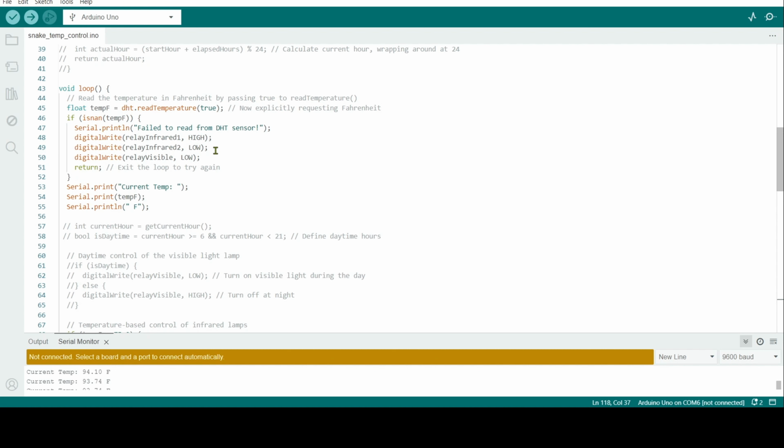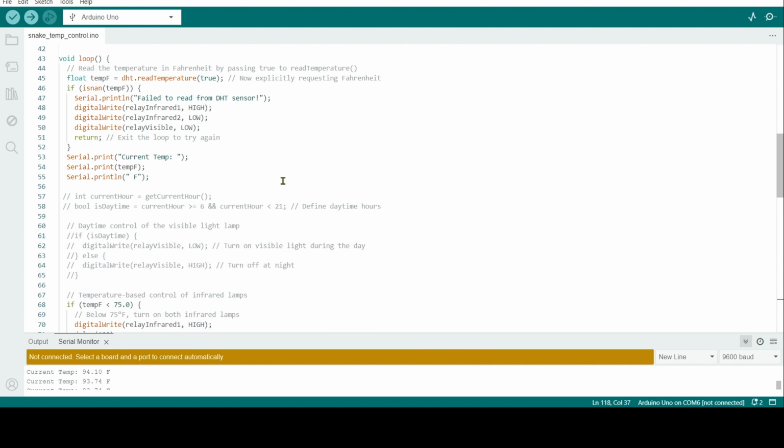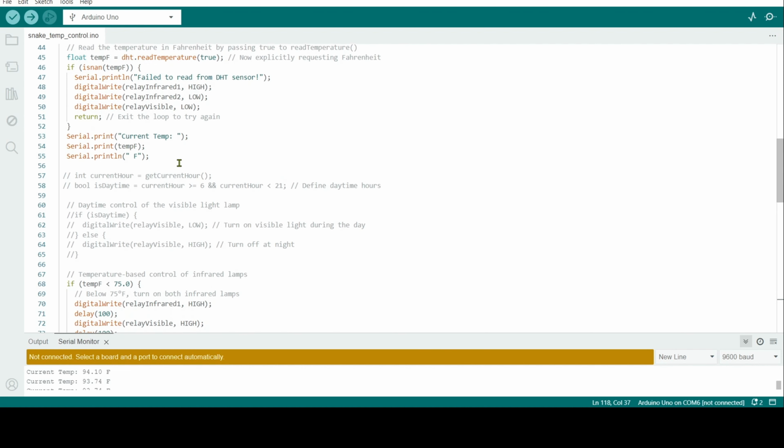If I lose that sensor at night and it's 30 degrees outside and my furnace doesn't kick on, ultimate fault state, we fault to just one relay on. Not ideal, could potentially be dangerous for the snake, but the best failure that I have right now would be to have one light on, and then catch it, of course, when I get back home.